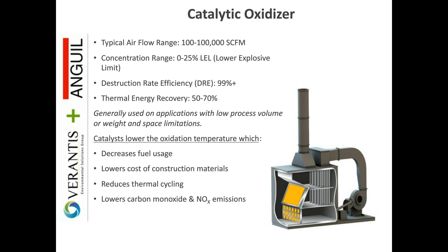The downside is that the limit on the heat exchanger here is roughly 50%, on the high end 70%. When you run it through the system and through the calculations, you'll see that it actually ends up consuming quite a bit more than an RTO does. I've got a slide coming up in a little bit that will compare all these technologies under the same process conditions, so you'll get a pretty good idea of the difference.